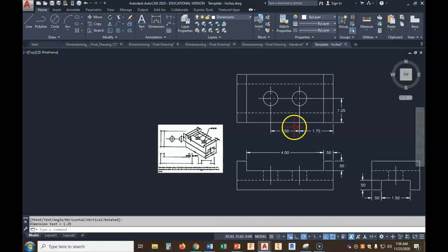And we don't want to tuck it inside the dimensions. So it either needs to be here or here, one of the two. Ideally, we would take it this way because that gets those numbers close together. But you may do that and see, wait a minute, I like it better up here. So I can either do it with a leader or I can do it with the diameter dimension.